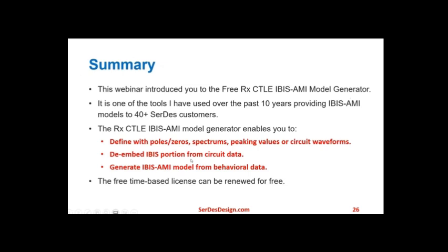So, summary. This webinar introduced you to the free Rx CTLE IBIS-AMI model generator. It is one of the tools I've used over the past 10 years, providing IBIS-AMI models to 40+ SerDes customers. The Rx SerDes IBIS-AMI model generator enables you to define the CTLE with poles and zeros, or with spectrums, or with peaking values, or with circuit waveforms.